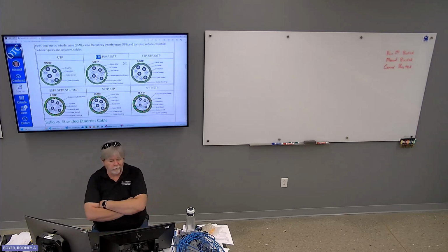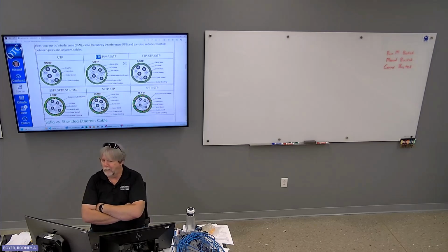The main reason for using shielded cable is in an industrial environment where you have a lot of electrical noise, especially whenever you have VFDs running motors, because they are basically giant radio transmitters. Oh, yeah. So they use filters for those, right? Yeah, put it in line.